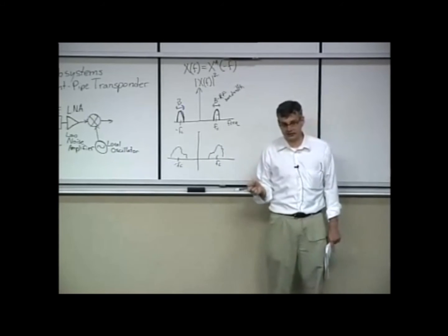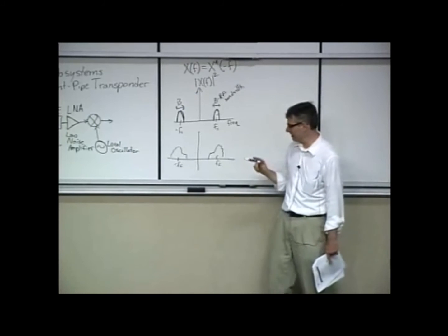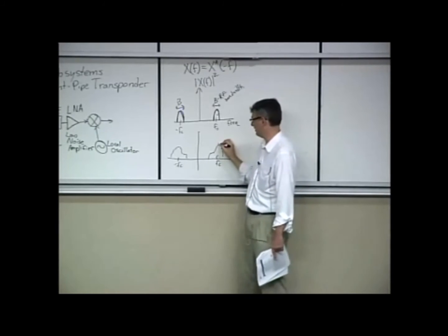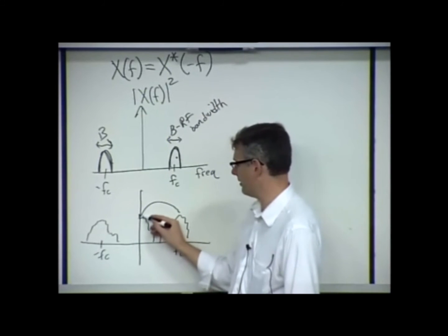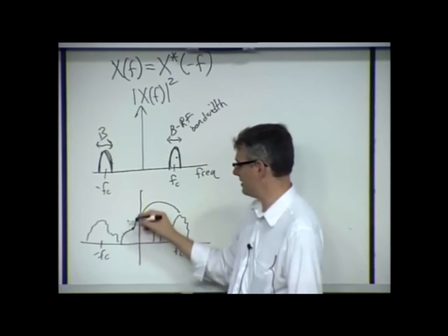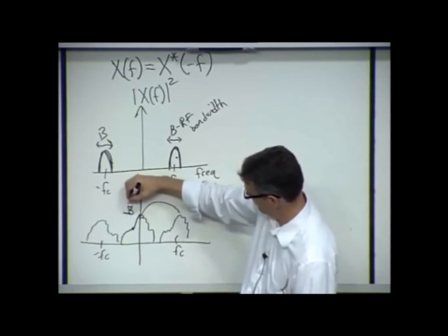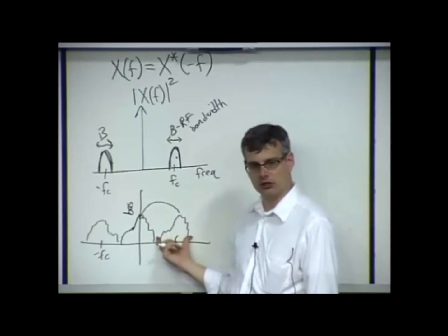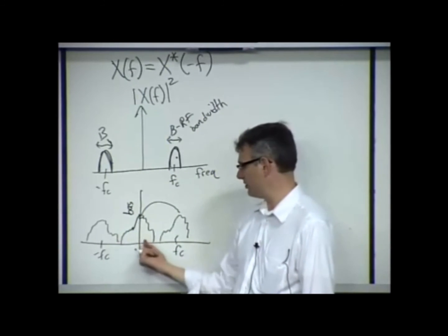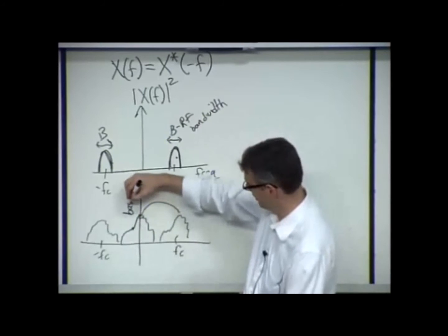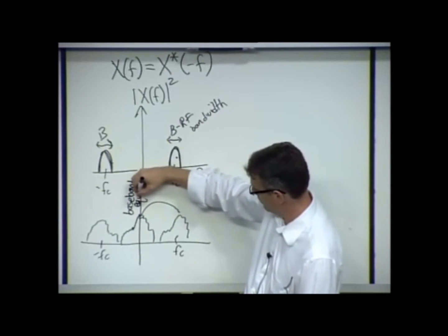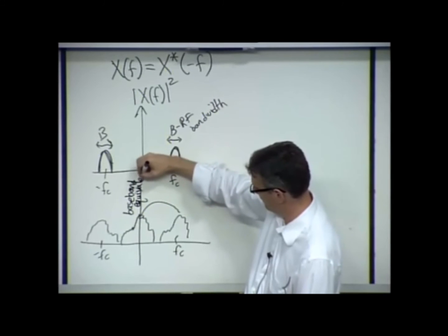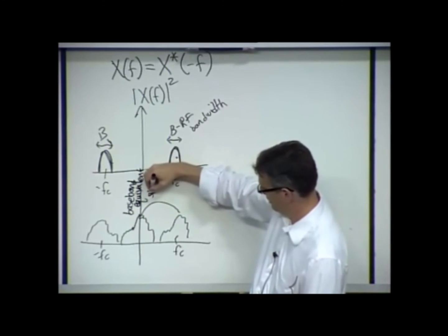For analytic convenience, however, telecommunications engineers, particularly those in wireless communications, like to move this down and call this the baseband equivalent spectrum, where they take one lobe and move it down so that the center frequency is now at 0. This is called baseband equivalent signal modeling.